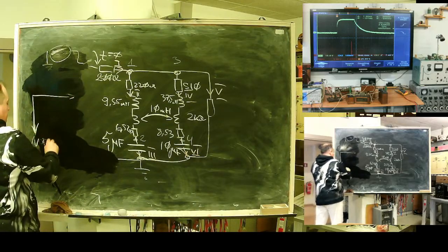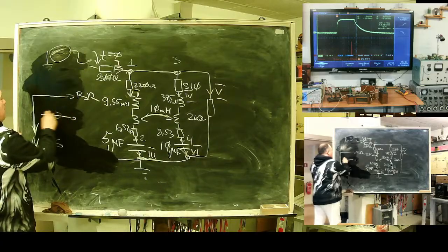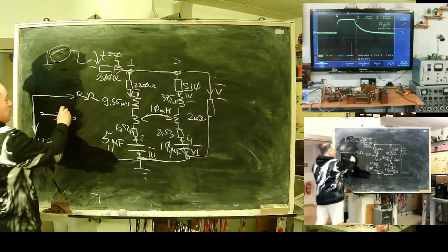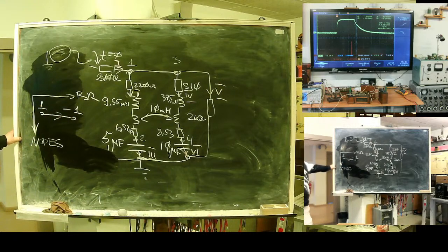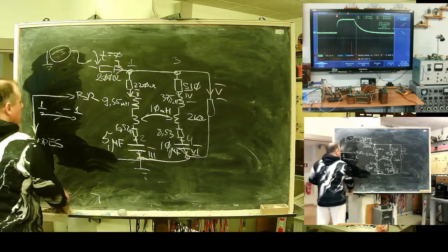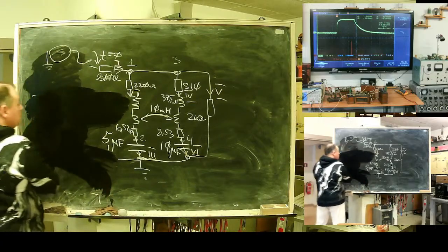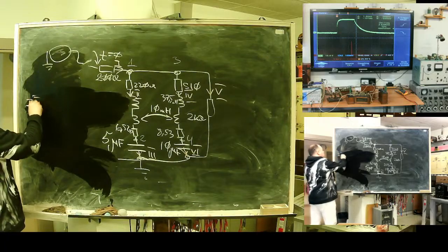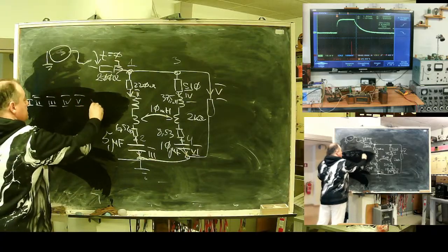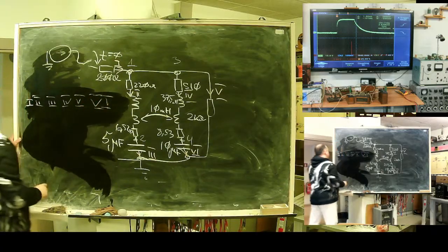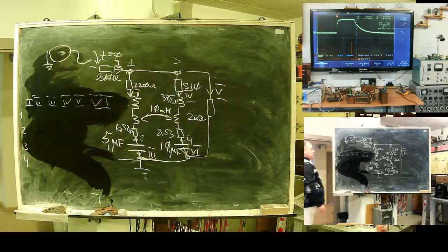Nodes, branches. If a branch falls into a node, you write -1. If it falls from, you write 1. No connection, write 0. In my case, I need 6 branches: 1, 2, 3, 4, 5, 6. And 4 nodes: 1, 2, 3, 4.